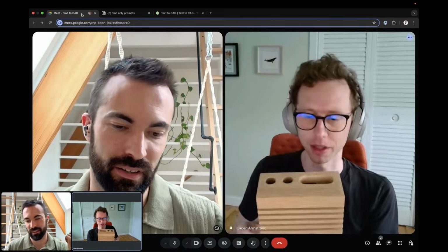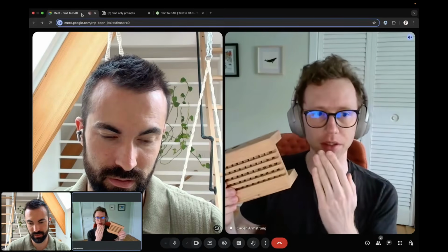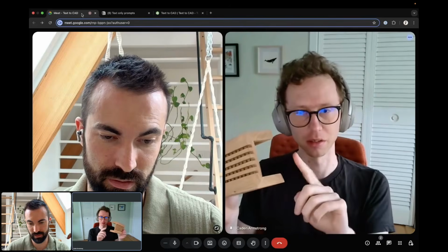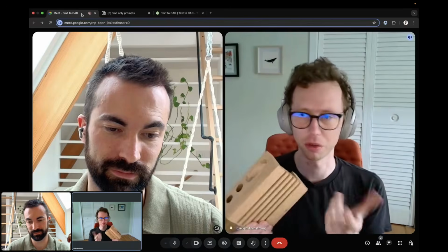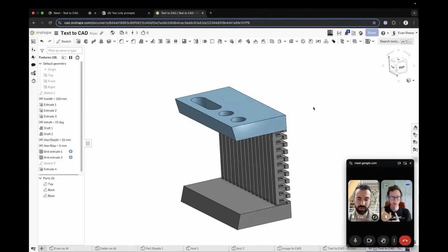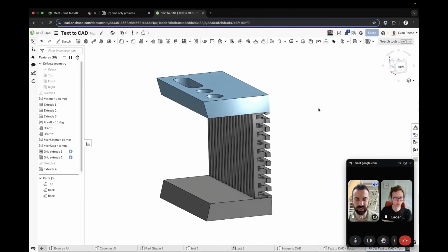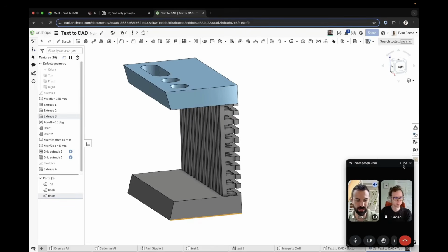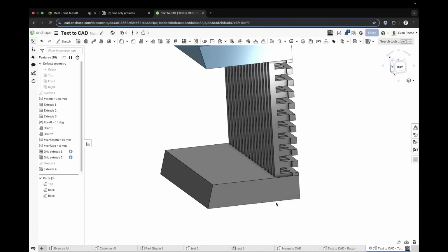But I think the interesting thing is that the base, you started with the correct dimension and you drafted outward. So this edge comes out, whereas mine drafts in. So they're slightly different. So again, that's an interpretation of, I'm saying it has a draft to it and I didn't specify direction. Actually, I think it's probably safe to argue that it should have drafted in because I can see here that this actually no longer meets the spec of the prompt. Yeah.